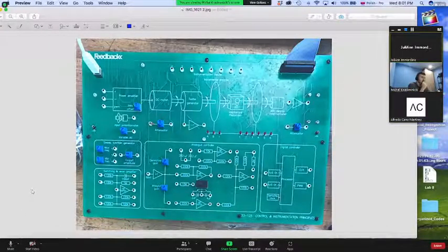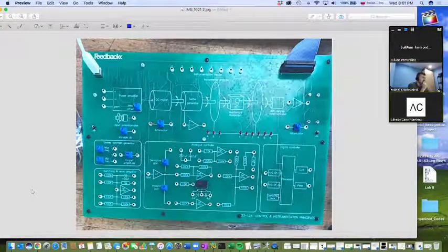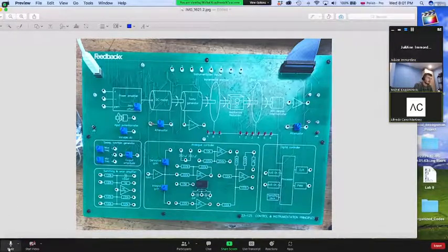Could we also use the power amplifier to increase the gain? I mean, that relates to the signal, because you have a DC motor, and you know from your previous experience that these things usually require high currents. So the power amplifier is actually amplifying the current that goes through the motor. It doesn't really function as a gain per se, because you cannot really amplify how much current goes through the motor, except through the signal that you provide to the power amplifier.